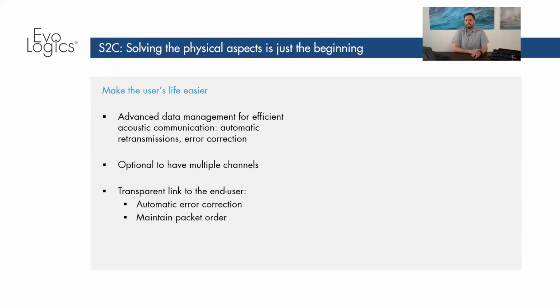And you can also have this transparent link, basically. You connect the modem as if you were connecting a cable, and you don't have to take care of anything particular. We have also developed some special protocols to take transmission delays into consideration. Some sensors are sensitive, or their software rather is sensitive to timeouts. And since you are transmitting in water, the lag is higher, much higher. So we have some workarounds where we basically trick the sensor and the computer into thinking they are talking to each other directly at a shorter distance, but we are doing some magic in between.